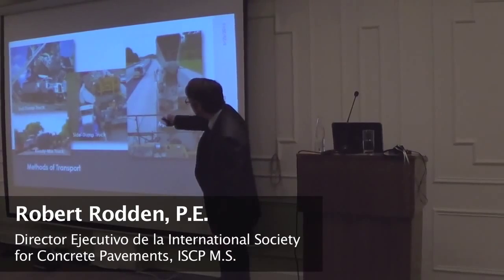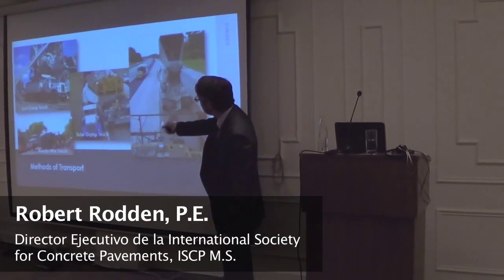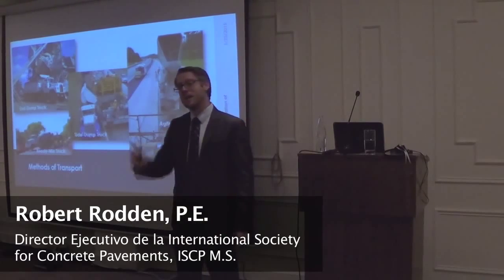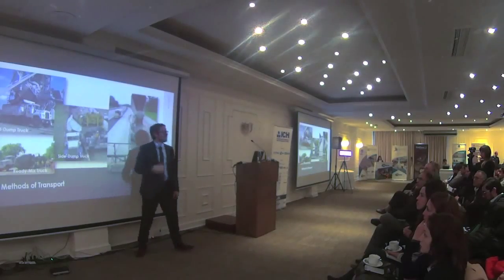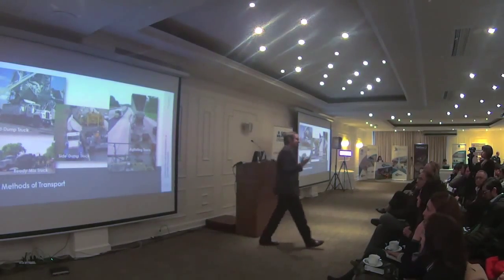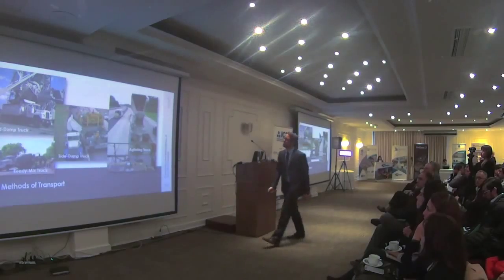If you use a side dump truck like we see here in the middle, it just dumps to the side instead of out the back end. Now we can have a haul road that goes in one direction. All the trucks will enter in, side dump, and continue on. The next truck comes in right behind it in the queue. So there's all these little logistical things based on space limitations that might change the contractor that wins the low bid because this contractor had this equipment. So it's not as simple as just letting the project. There's all these other parts that move.